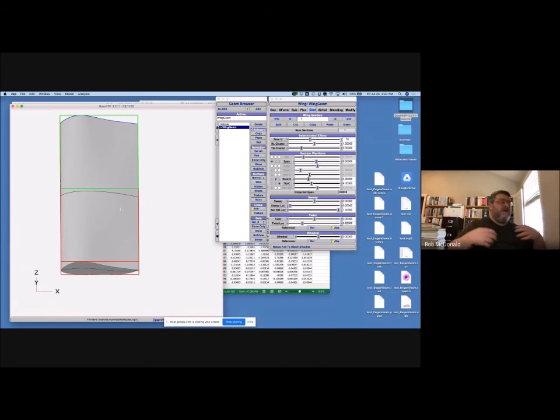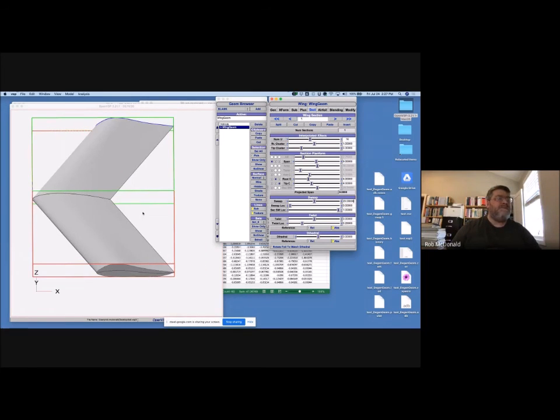And for that, you'll pretty much always have a normal wing and a tail, because that's the best way to get lots of stability. So most blended wings and most flying wings will use a combination. They'll have some moderate amount of sweep in them, and they'll have some amount of twist. And they're not going to have hugely cambered airfoils, because having a lot of camber in your airfoil is just adding a very strong destabilizing moment that you've got to counteract with more twist and more sweep and more reflex.